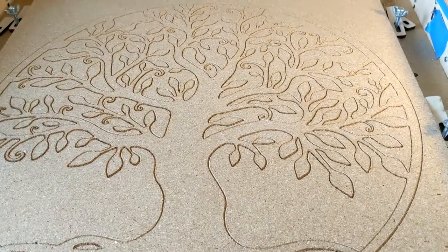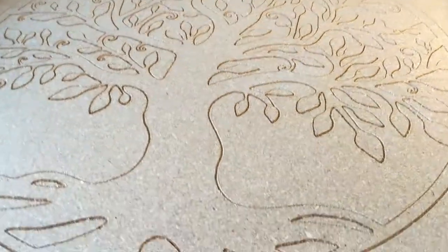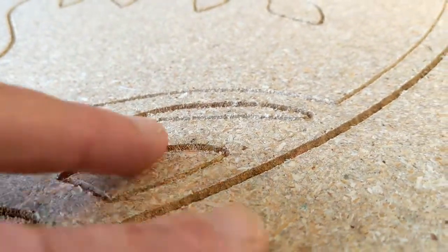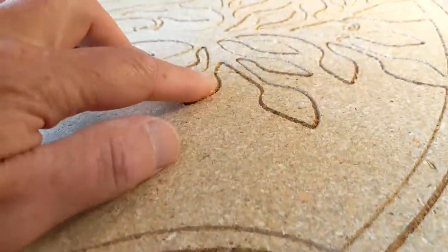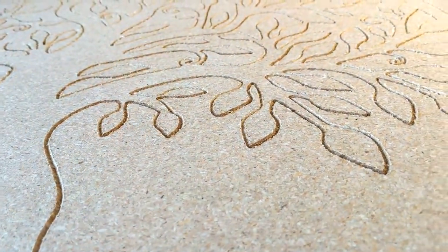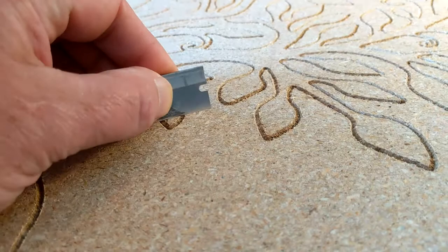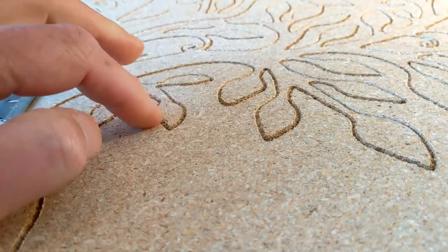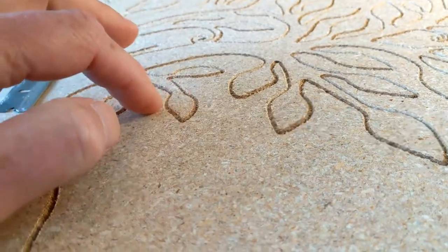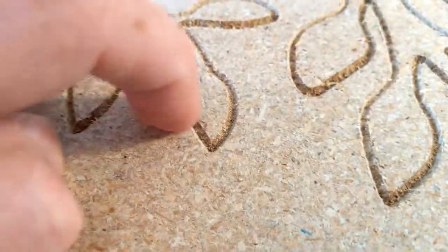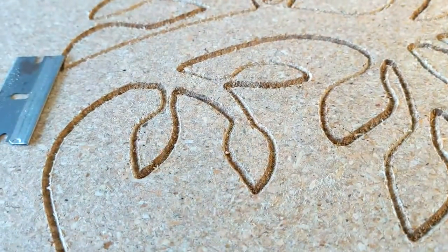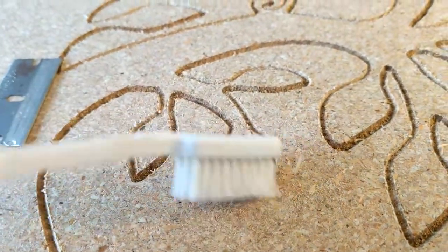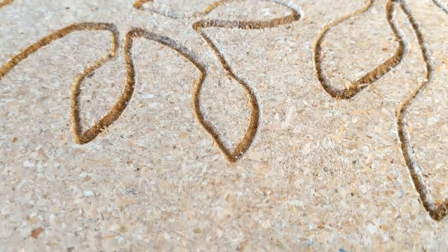After the board is cut, this beautiful cut, I want you to take a close look at this. I've got a lot of burr hanging around on these cuts. So what I'm just going to do is take a razor blade, scrape the whole thing, and that smooths everything out, breaks off all the little chips. And then inside is a lot of debris. I just take a used toothbrush, clean it out, and everything looks good.